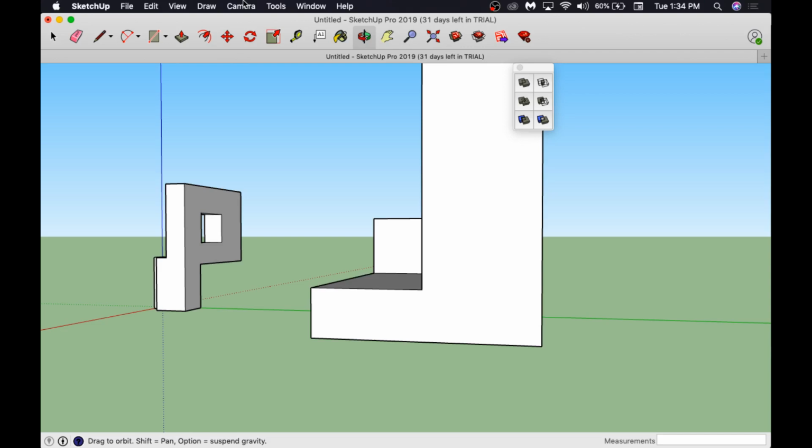Orthographics can, in a kind of interesting way, if we control our line weights. We've done that before. We push the line weights back and we can get some depth in the drawing. So what else? Anybody else? No, we see proportions even better in orthographic because we can see the exact size of things. Anybody?